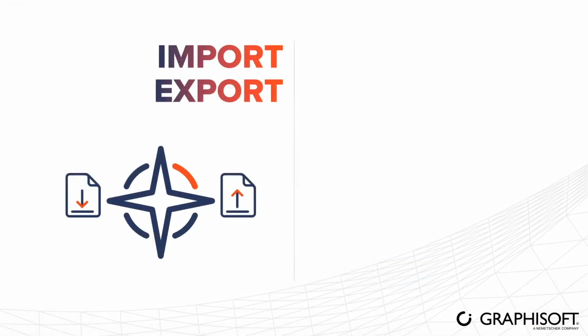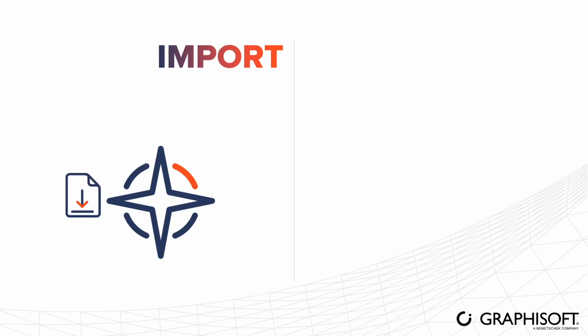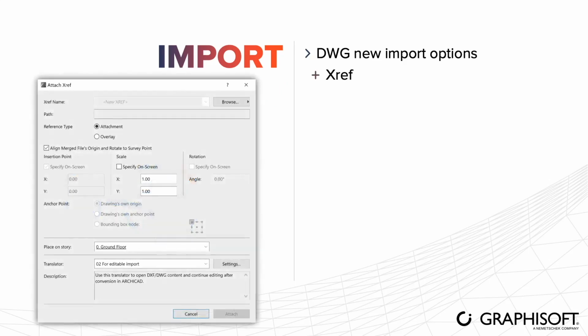Having the survey point in the project improves our model export and import workflows. Let's see what possibilities we have when it comes to import. Regarding the DWG, we can choose either if we want to link the drawing as an XREF or if we want to merge it.